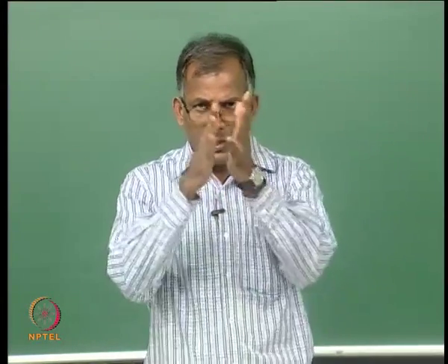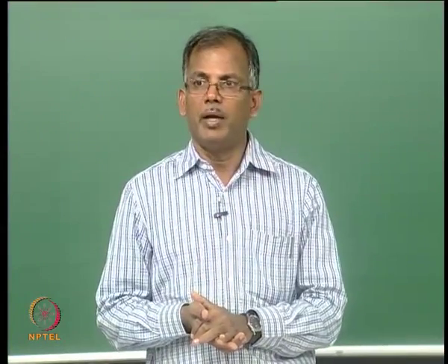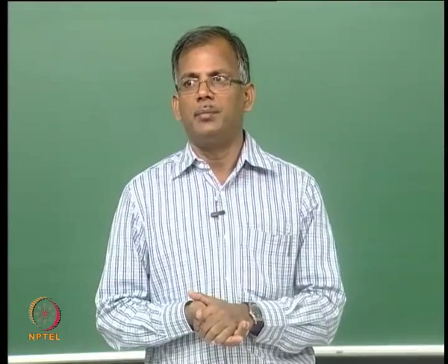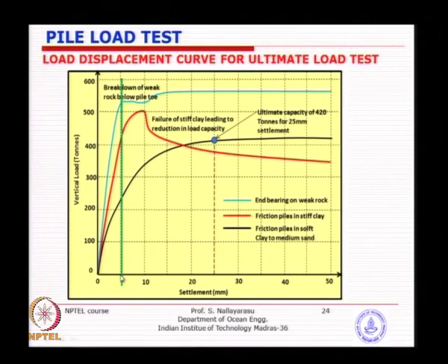So that corresponds to the ultimate failure. Whether you want to consider it here for steel piles has to be decided by what ultimate failure state you want to define. So once you define that limiting load or limiting displacement, then you can go to the graph and take this as my ultimate failure load of the pile, beyond which we will not be able to take it.